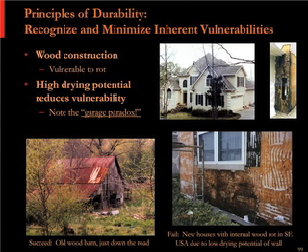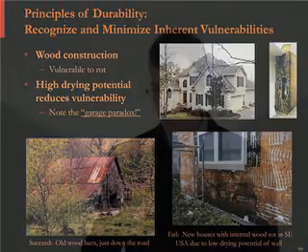Kind of a similar story on those EIFS or synthetic stucco-clad houses in the southeast, in North Carolina and in Georgia. So, 3 or 4 year old houses that are failing really badly with wood rot. The big story here was the drying potential. So they had interior vapor retarders.